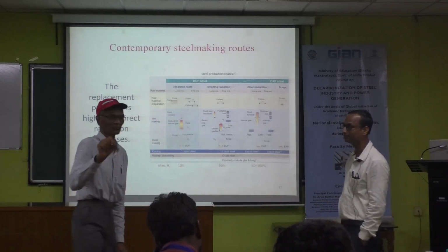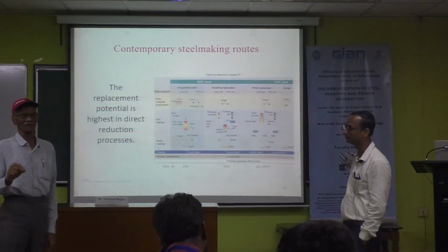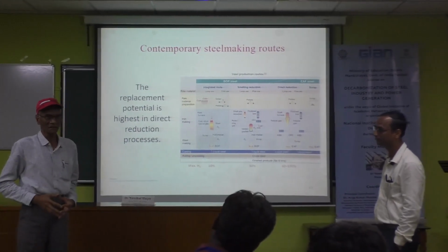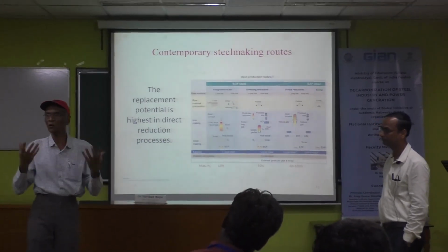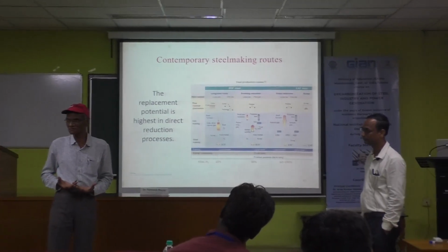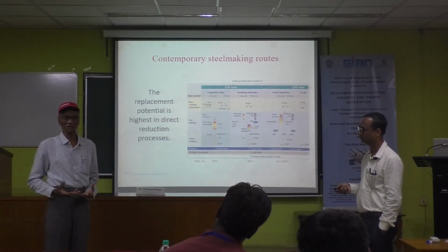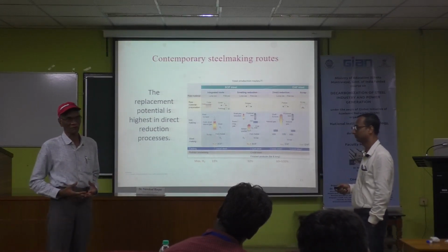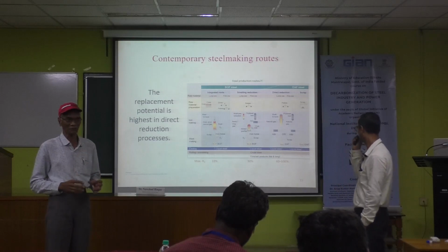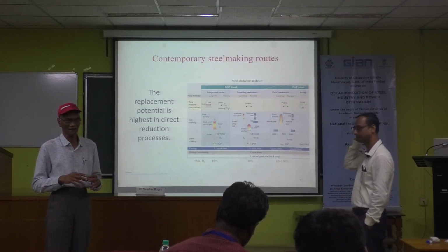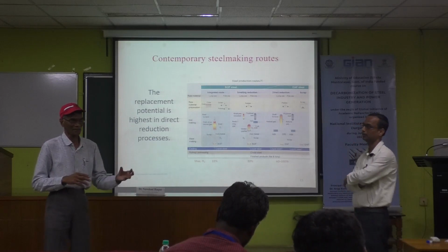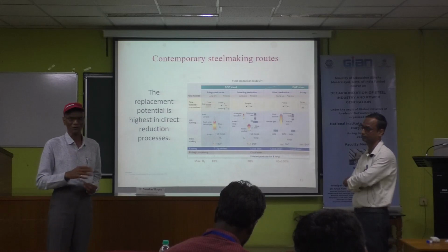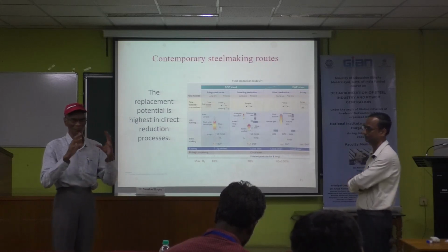Very important: the trickiest part in the blast furnace is that coke itself is a column of support to the burden. If there is no coke, where will you hold this material? It is practically impossible to convert iron ore, sinter or pellets to liquid metal. That figure is 170 kg per ton of hot metal. That is a minimum; maybe we can think of 150 by doing many things. Below that you cannot go, because there must be a physical support to the burden.